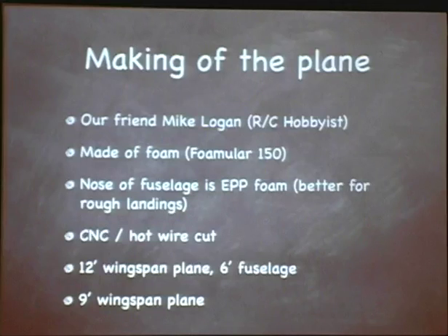He's CNC cutting it using a hot wire, which is where you end up with basically two poles at the end of a table and a hot wire stretched between them, and the poles move on stepper motors so that a computer can guide it to cut the parts out. Although I think he might not even be doing a computer layout, just stepping them by hand.